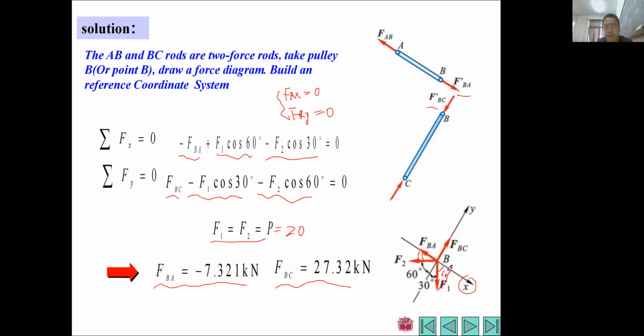You see, I can give you an example. So F1, actually we know its intersect angle is 30 here. Actually here, F1 times cosine 30 will be its y component. Actually, we can also use F1 times sine 30. It will be its x component, right?